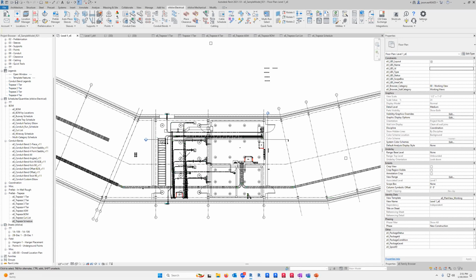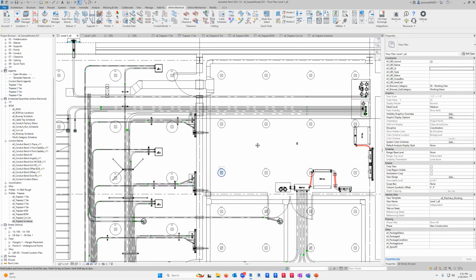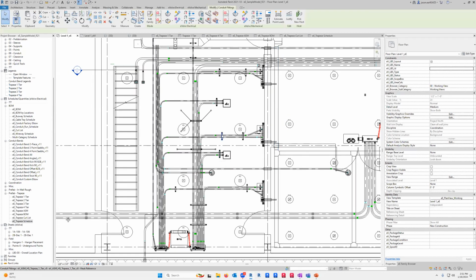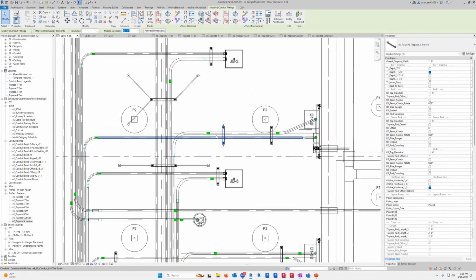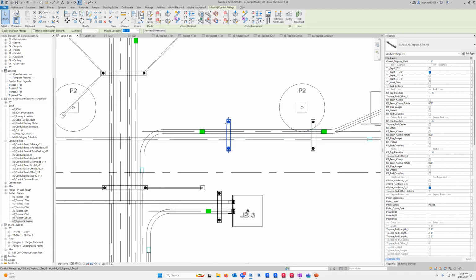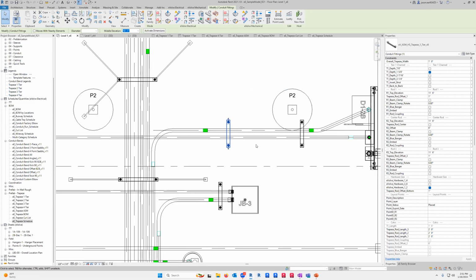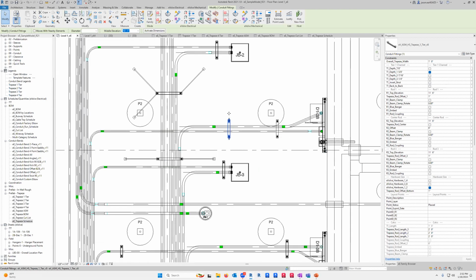If the reference planes get adjusted in the middle of coordinating a space, will all the related hanger attachments adjust to the new elevation, i.e., if there are changes with structural steel elevations? No, they won't. And ultimately, that's just how Revit works at the end of the day. The hanger does not know that the structure is there. Evolve can ask the model, is there structure there? And we set the parameter value. But there's no way to actually tie that parameter to that structure overhead. So if it does move, no, you're not going to know that.